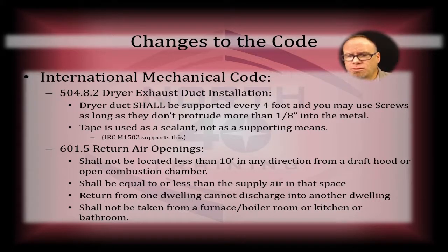Next portion, shall not be taken from a furnace or boiler room or kitchen or bathroom. Okay, now that's something you got to think about too. Us HVACR guys, refrigeration guys, electricians, we all throw around the terminology of mechanical room often. Okay, but mechanical room really is only a commercial application. It's an other than dwelling unit application. That's the term, an other than dwelling unit application for a mechanical room.